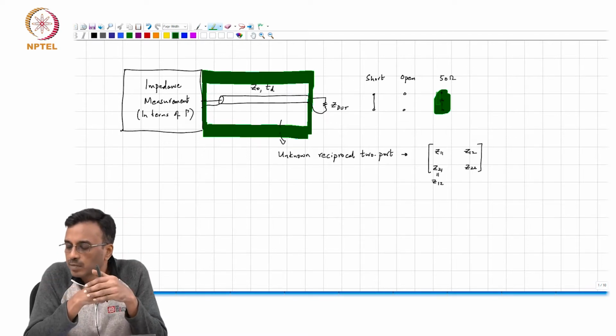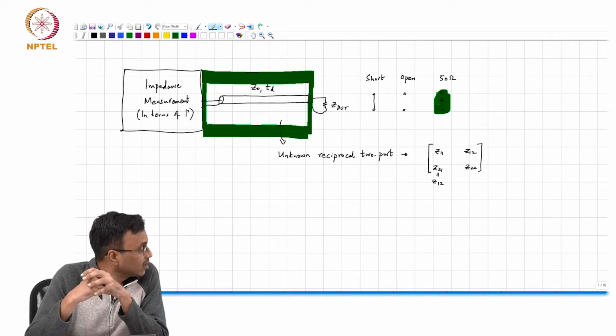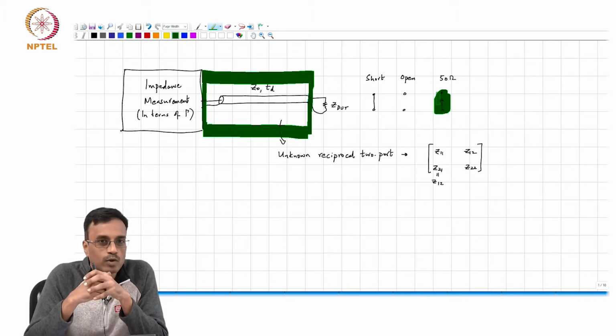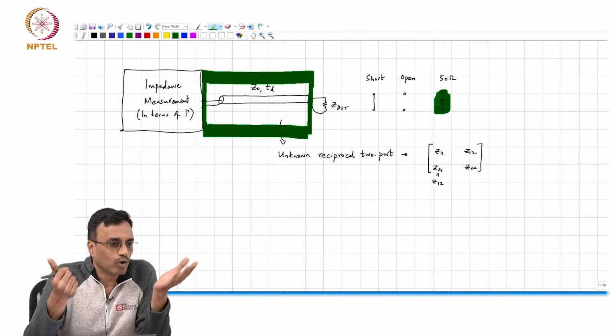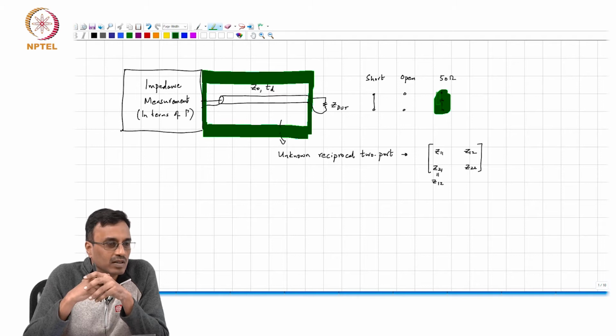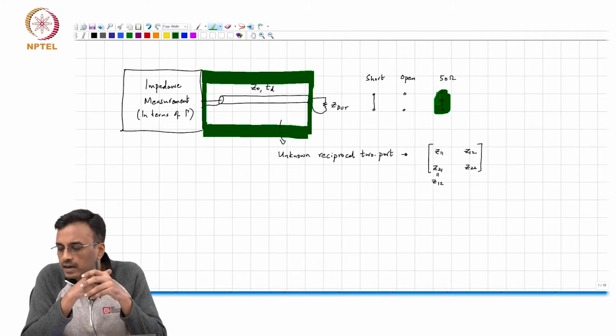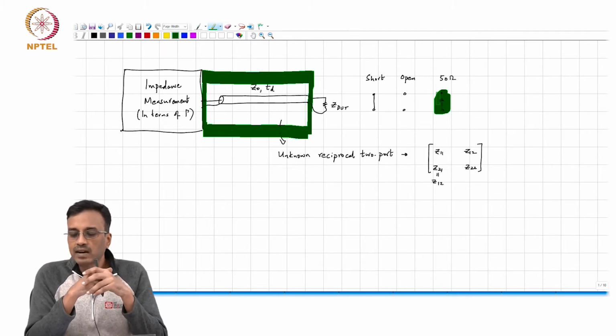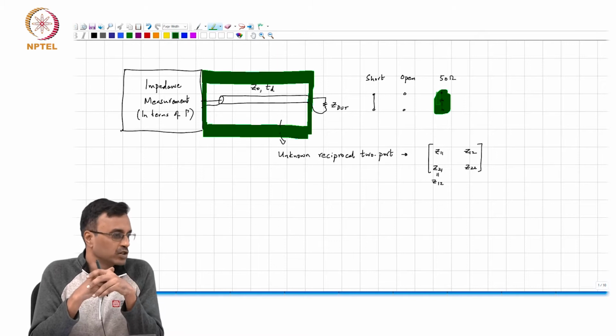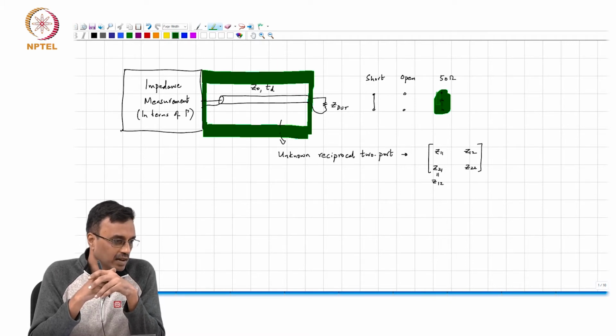So, if you thought it is 50 ohms, but then, like you do your homeworks, you basically cut corners, and then the 50 ohms is 54 ohms, right? Then all the measurements that you make will be off by 4 by 50, right? Simply a scaling error, right? Because Z naught will appear somewhere in all those calculations. Okay, and this notion of open and short also needs to be